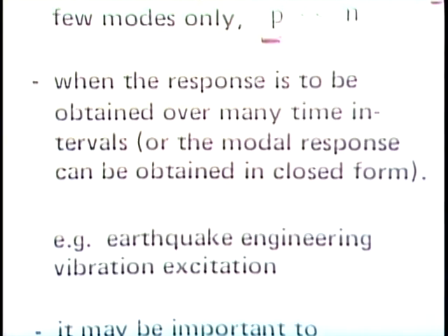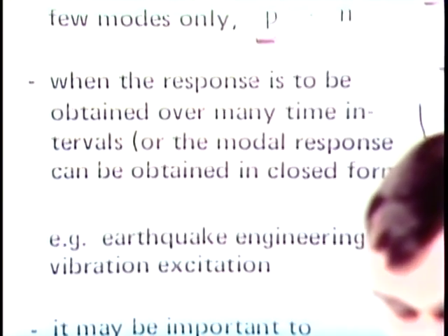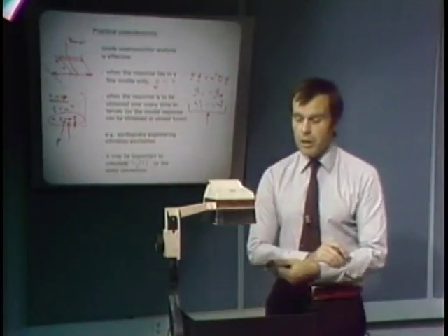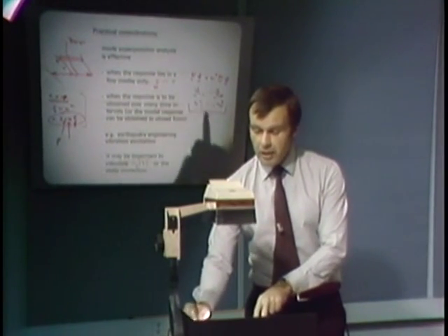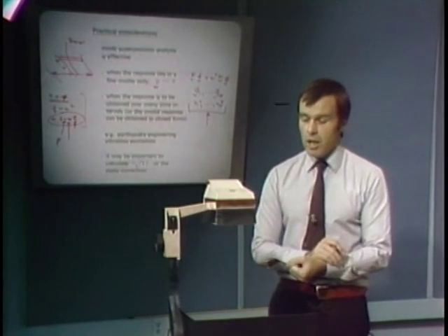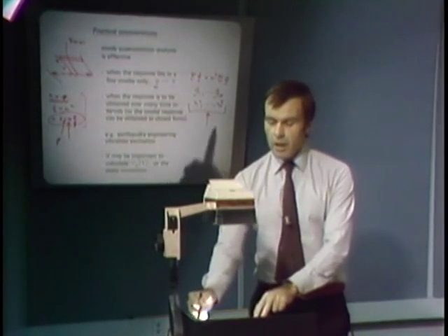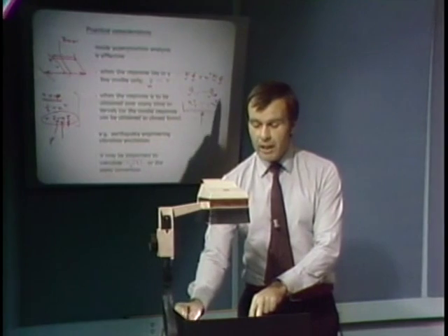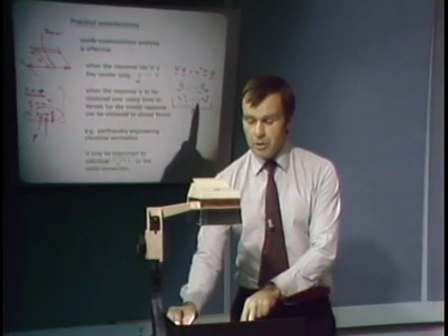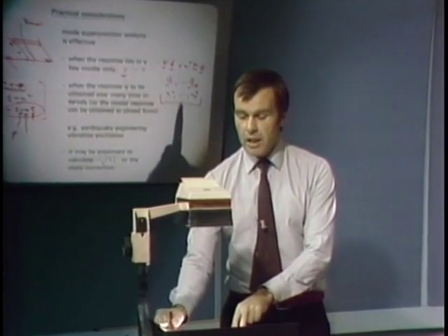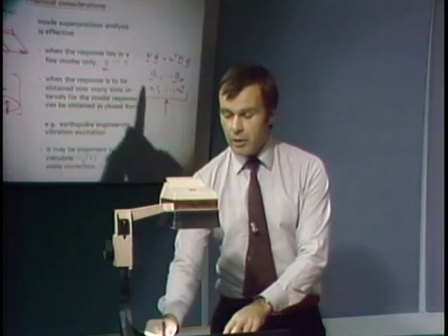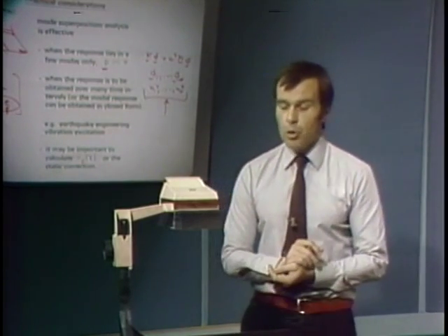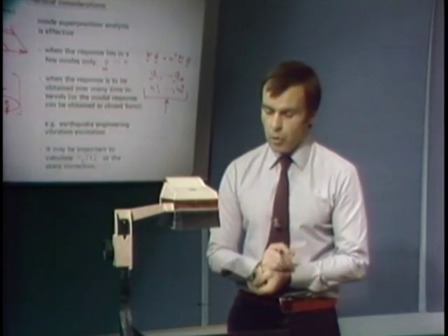Where the expense lies in mode superposition is really in the calculation of the required frequencies and mode shapes. And of course, this is exactly the subject of the next lecture, where I want to discuss with you the effective solution techniques for calculating these vectors and frequencies. Mode superposition analysis is effective altogether only when we can calculate these eigenvalues and eigenvectors in an effective way.